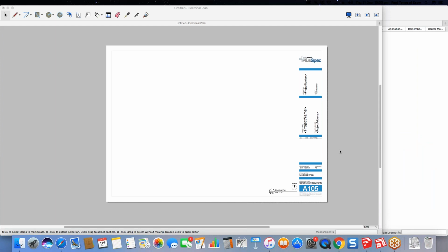Is there a way in Layout to do multiple wall line weights? So having, for example, a really heavy internal line or external line versus a thinner internal line? The answer is no. It's a section plane, section cut. So typically, I know everyone has their different drafting style, but typically the line weights are derived from the cut. So whatever is cut is shown at the same thickness, really. It's cut straight through it. That's the plane. That's the global change. So that's inside of PlusSpec for SketchUp.